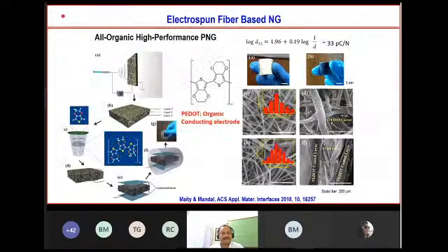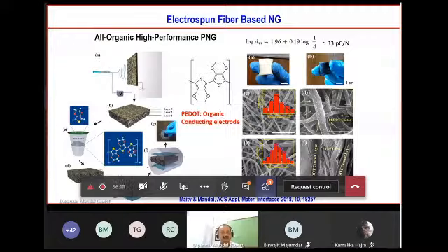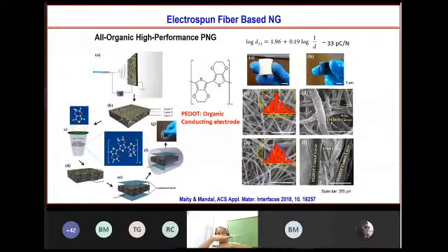In order to make the nanogenerator, one has to make the piezoelectric material here, and then top and bottom we have to make the metallic electrodes in order to collect the charges. So once we apply the external pressure here, then the polarization gets changed, dP by del stress, and then if we connect an external load, the current basically flows. So the main problem with polymer nanofibers or any organic materials is that one has to make the metallic electrode, right?